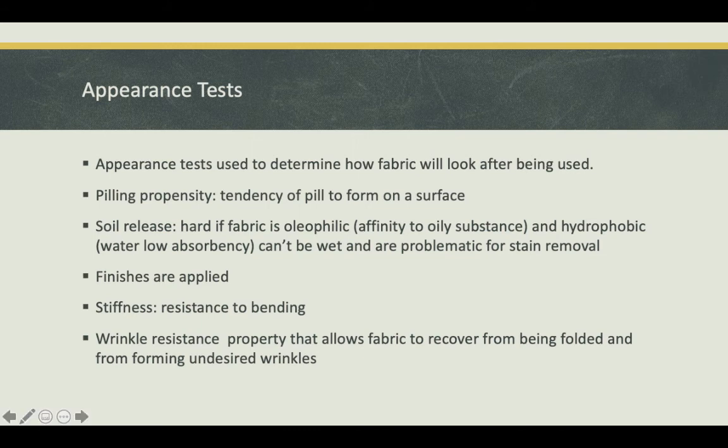The biggest issue is when a fabric is oleophilic, so it absorbs oil, and yet it's hydrophobic. It really can't take the water, because then it can't get wet enough with the detergent to clean it and remove the stain. So cheap fabric that is oleophilic, it absorbs the oil, and it's hydrophobic, it doesn't like water. Those are the worst. Those are the cheap fabrics that will stain, and you can't get those stains out no matter how many times you wash them. So sometimes we apply finishes, obviously, and finishes help with the appearance.